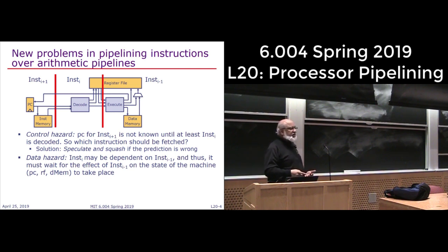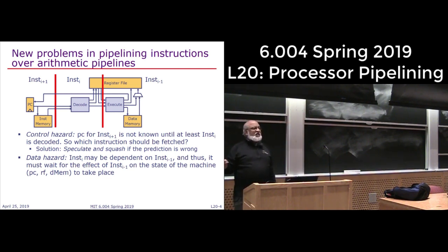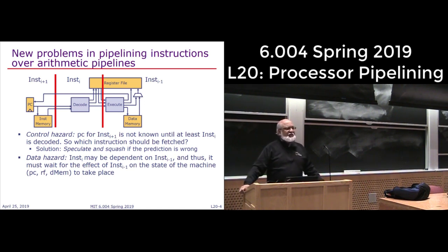But here we are being very eager. There is an instruction I-1 in the execute stage, and suppose it's going to update register R1, and it just so happens that the instruction in the decode stage wants to read R1. First of all, will it be able to read R1? Absolutely. Hardware doesn't stop it. Go and read the register file anytime you want. It just so happens that the register file contains stale values at that point. It hasn't been updated yet. So these things are known as data hazards, data races, where you read it too fast. You have to wait until the right value is available.